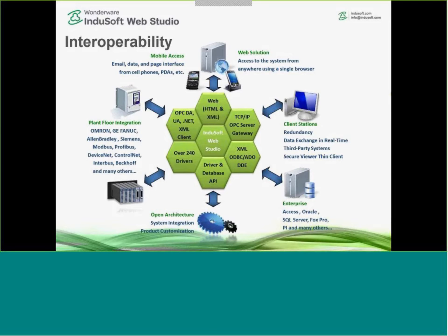includes protocols for devices like Omron PLCs, GE PLCs, Allen Bradley, Siemens, Modbus TCP, Modbus Serial, Modbus Plus, Profibus, DeviceNet, ControlNet, or even IT kind of protocols like SNMP, Simple Network Management Protocol, or even MQTT, which is an important protocol for IoT, Internet of Things. So in addition to the drivers, we also continue supporting our database interface, so you can very easily exchange data with databases, local databases, or even databases on the cloud like Microsoft Azure.